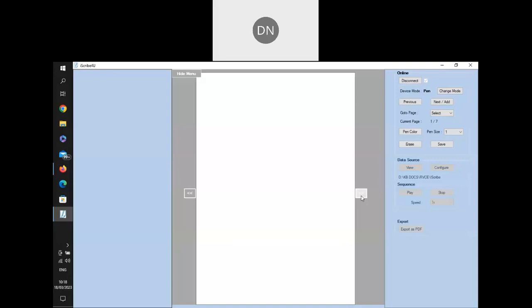Now we have other types of memory. That is a memory available in the DRAM family called a synchronous DRAM. So what is a synchronous DRAM? Synchronous DRAM is completely different from a normal asynchronous DRAM. One of the advantages of synchronous DRAM is that it supports word transfer and also block transfer, or page transfer. So it has the capability of transferring one word or one block.